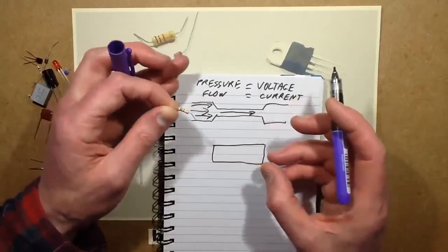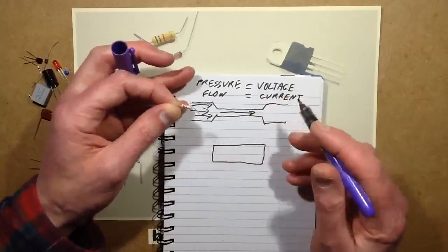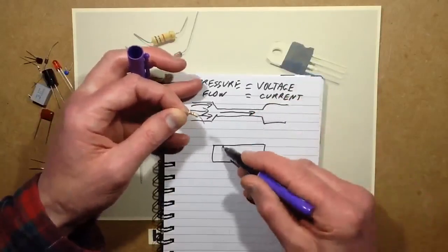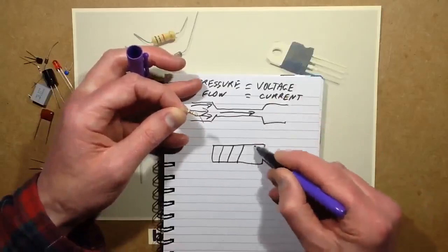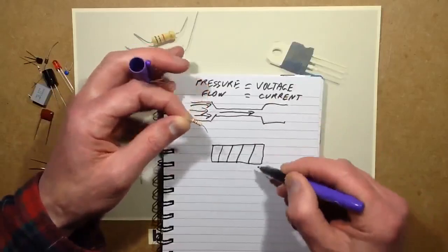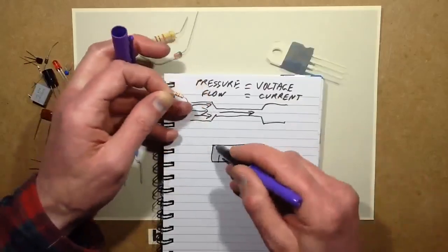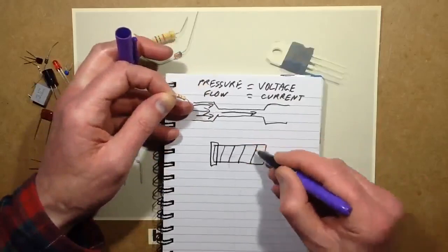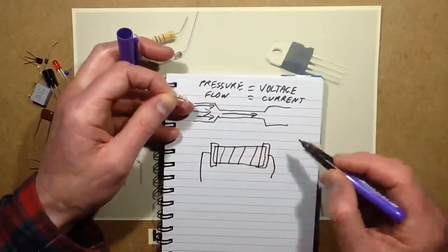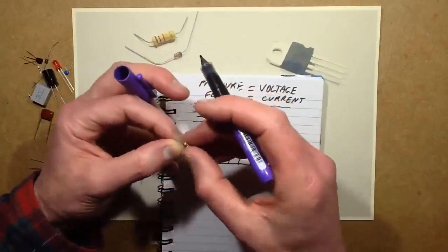And the thicker the carbon coating on it and the type of the composition they're putting on it, the more conductive it will be. But then they can fine-tune that. They actually cut a spiral round it, and that creates a long, thin path of the carbon, and that increases the value of the resistance. And once they've done that, they put a metal cap on the end with the leads coming off, and they dip it in a sort of, I suppose it's a lacquer really.